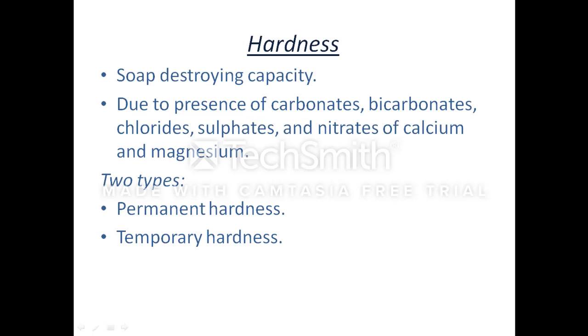Now coming on to the hardness of water. What is hardness? You may be knowing that hardness is that characteristic of water which prevents formation of lather with soap, or we can say it is the soap destroying capacity. Hence hardness is not a favorable characteristic. The hardness is caused by the presence of carbonates, bicarbonates, sulfates, chlorides, and nitrates of calcium and magnesium.